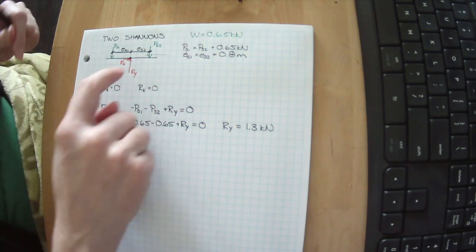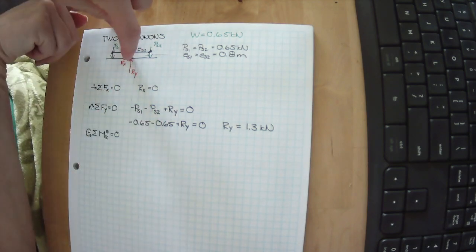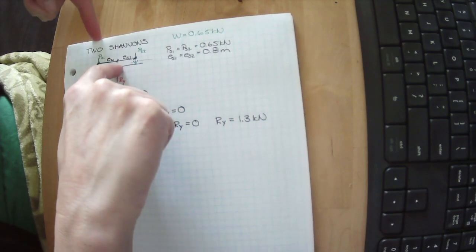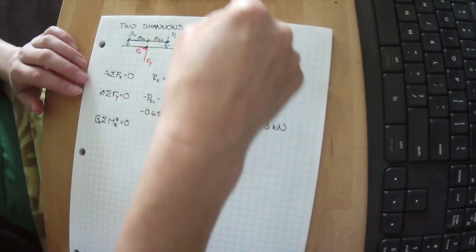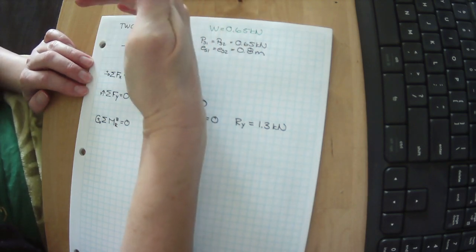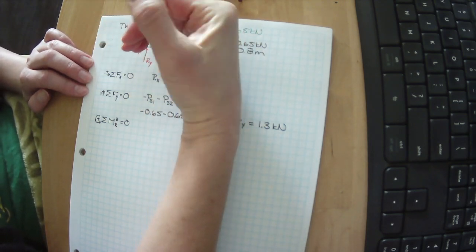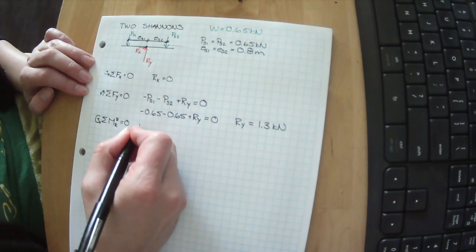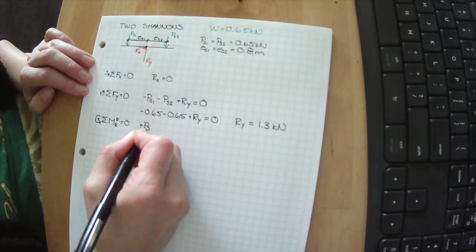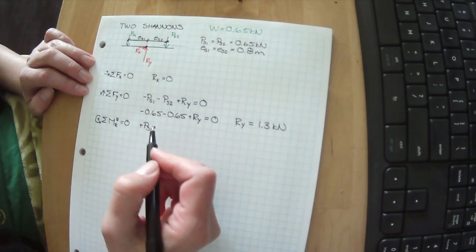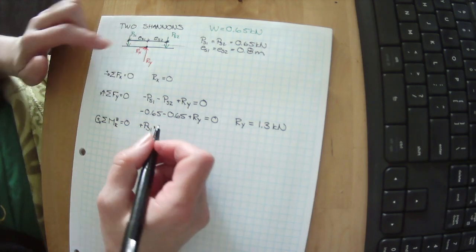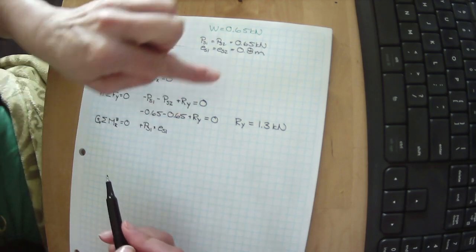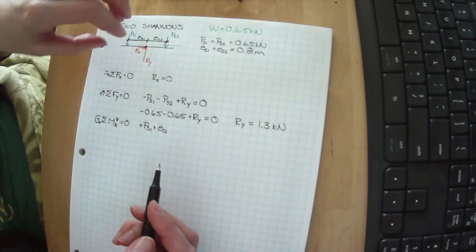Let's formalize that. So if we put a thumbtack right here, PS1 is some distance away from our centroid, and it tries to cause our object to spin in that direction. So if I curl my fingers in the direction it's trying to spin, and then point my thumb, that means it's spinning in the positive direction. So PS1 times, and remember, to be a moment, you need a force and an eccentricity, so PS1 times ES1, spinning in the positive direction, is trying to rotate this object.